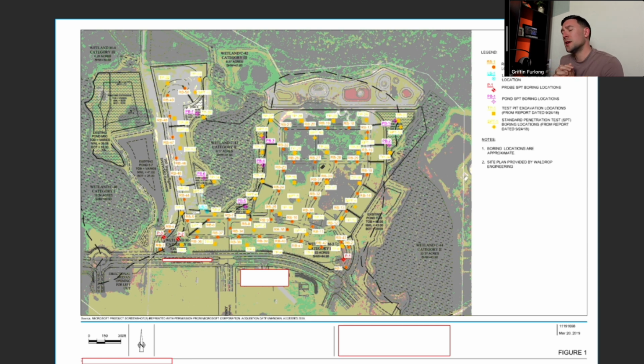For the land development engineers, we are designing the stormwater management system for the site, and it's absolutely important to know where that groundwater table exists. The reason why this is important is because if we do not know where the groundwater table or seasonal high water tables exist, how do we know where to design our road elevations and our home elevations?